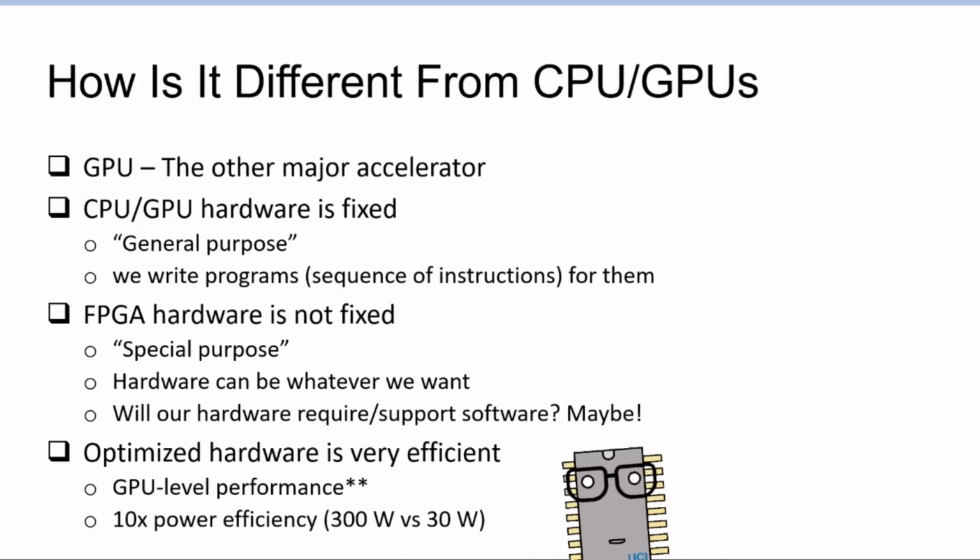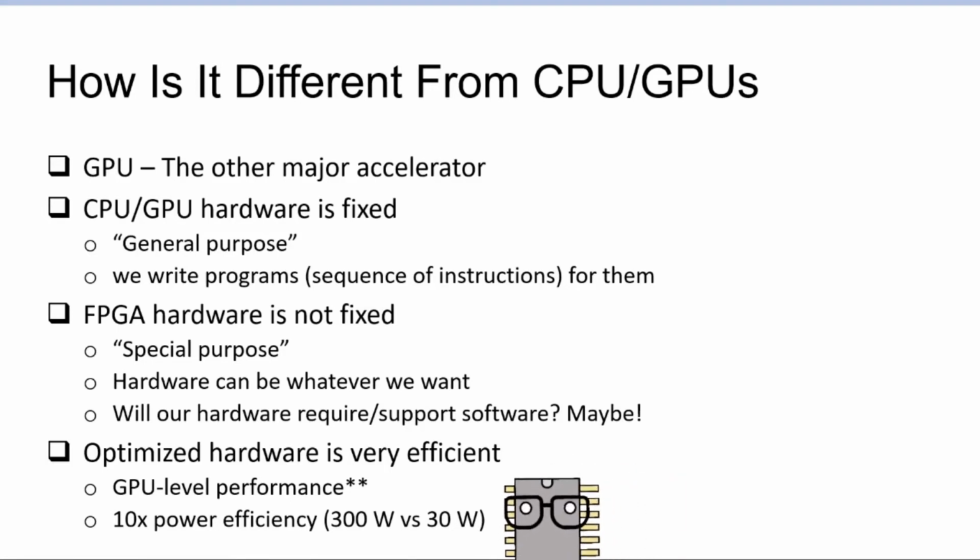If it's a very irregular kind of application, if you're doing shortest paths on graphs for example, or bit twiddling because you're doing cryptographic hashing or something like that, FPGAs are typically better in terms of power. But the real benefit of FPGAs comes from the better power efficiency, typically an order of magnitude. Similarly positioned FPGAs and GPUs typically do come at a significant power efficiency differential.